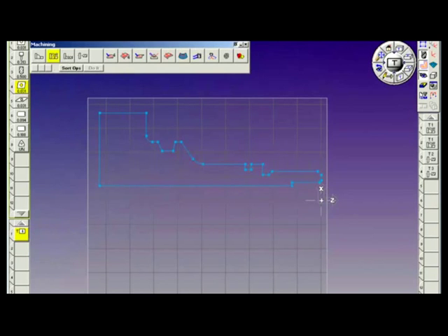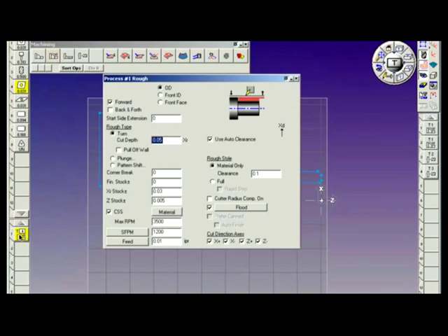and we're going to bring down the rough machining tile right on top of that process tile. In this particular operation, we're going to do the machining on the front ID. Notice that the graphics changed to represent an arrow up and an arrow down. We're using auto clearance, so those values are determined for us automatically. Forward spindle direction, my cut depth will be 30 thousandths radially. It's a smaller diameter bar, and we don't want to push it with 50 thousandths. I think we can take a couple of 30 thousandths passes.